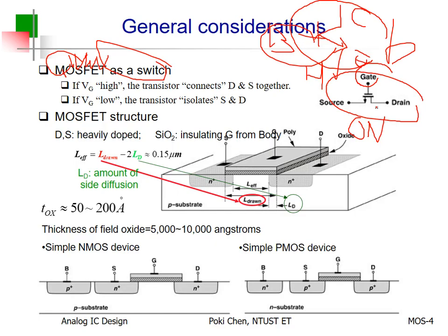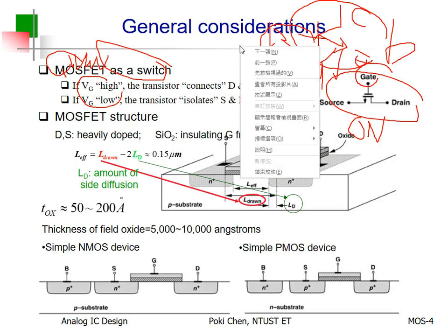Yeah. So to get a better understanding, this is for NMOS, all right? For PMOS, the polarity is reversed. So you need to apply 0 for on, 1 for off, right? And this is the reason why, okay, later in the symbol, we have a bubble for the gate of PMOS. Bubble means not, inverted, that is what we mean. Anyway, to get a better understanding,